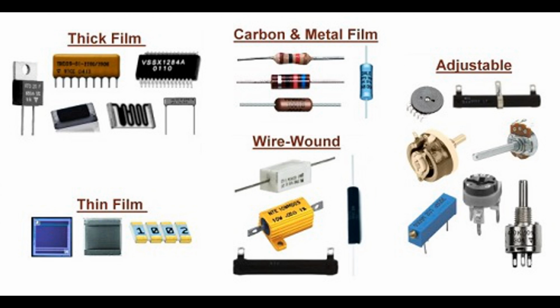Series circuit. Voltage division occurs in a simple series circuit where 2 or more resistors are connected end-to-end. The total voltage across the series combination is divided among the resistors according to their resistance values. How voltage division works. When resistors R1 and R2 are connected in series across a voltage source, V, the voltage across each resistor can be found using the following formula.